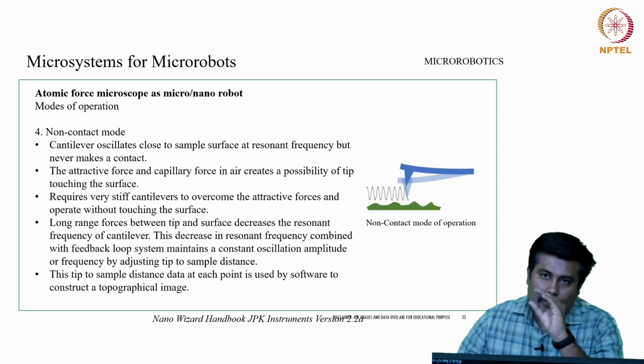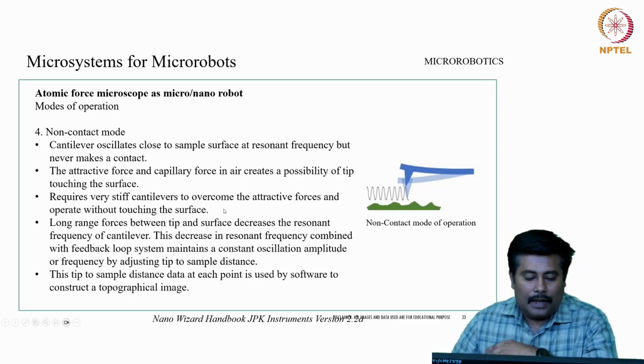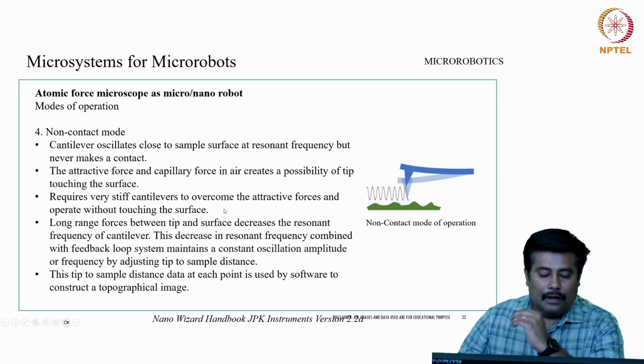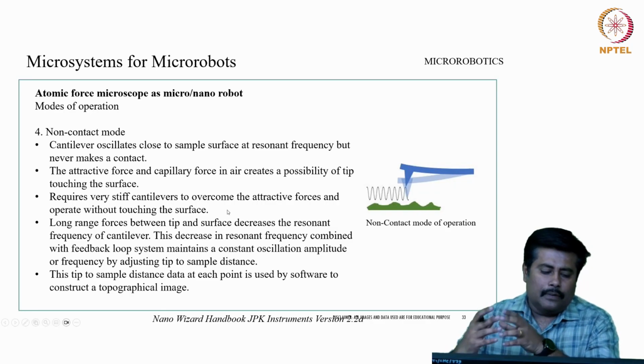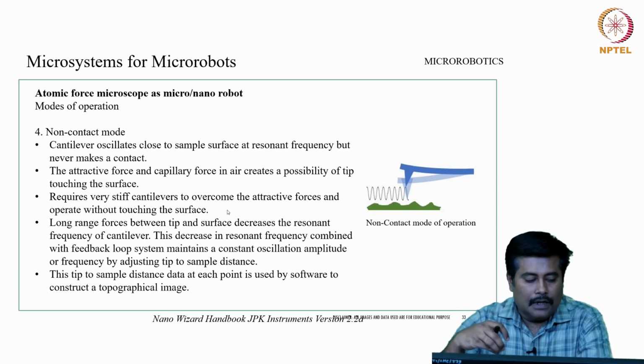So, there is a force which is exerted. There will be an attractive force, and a capillary force in air creates the possibility of the tip touching the surface. It requires very stiff cantilevers to overcome the attractive forces and operate without touching the surfaces.